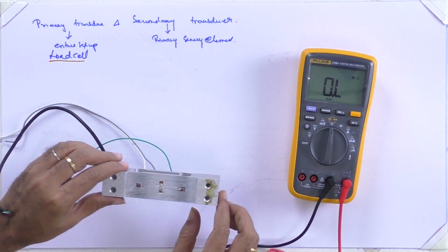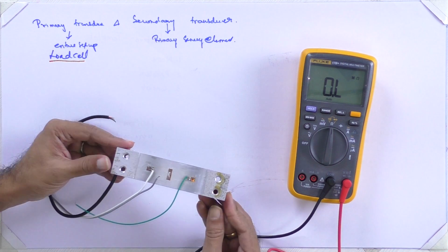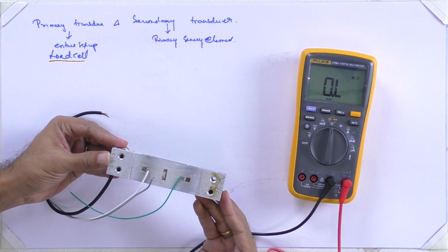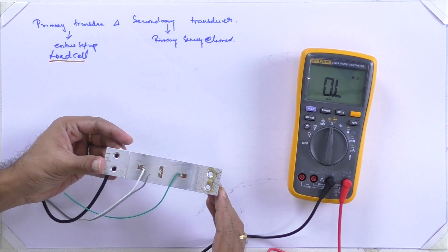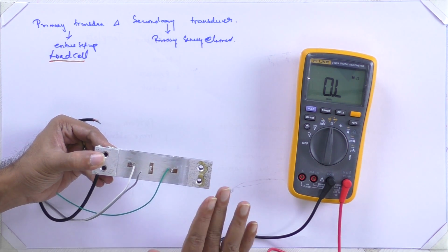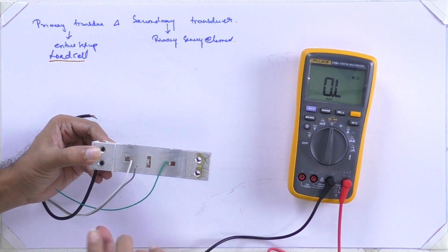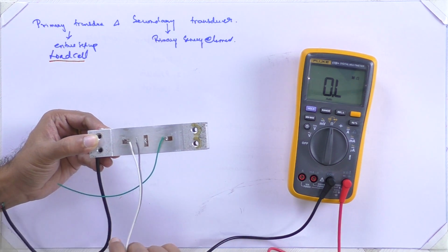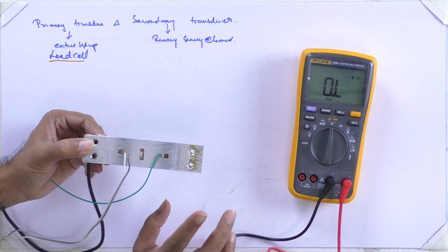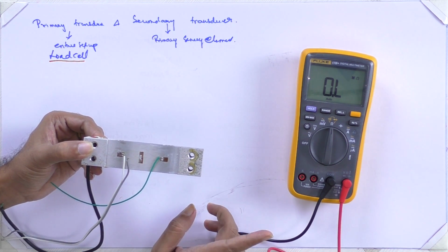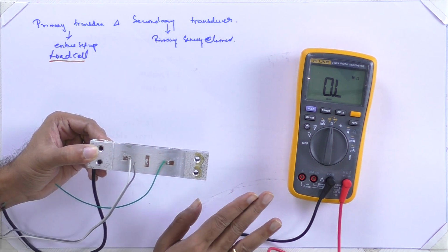Okay, so now you have been exposed to the load cell. This is a load cell for measuring weight. In your laboratory, you will be having this kind of experiment to measure weight from the load cell, and from the load cell you will be able to get the output weight. We will be calibrating the voltage that we get from the Wheatstone's bridge to weight. We will be directly measuring the weight out of the load cell because the voltage is calibrated to weight.